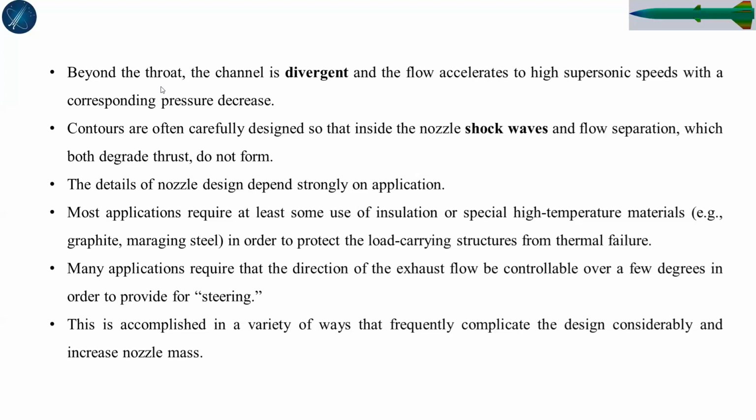Graphite is also one of the materials for very sensitive regions of the nozzle. So in order to protect the load carrying structure from thermal failure, we must use this material. Many applications require that the direction of the exhaust flow be controllable over a few degrees in order to provide a steering mechanism.